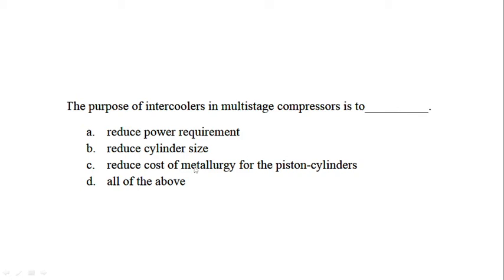So this will help to reduce the cylinder size, because we can handle the same volume in the next stage also, and reduce the power input in the next compressor. It also protects the parts of the compressor in the next stage, so we can choose a low cost material of construction for the piston and cylinders.